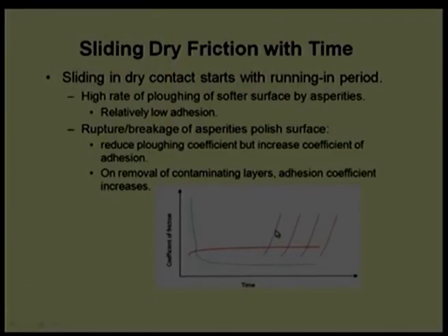It may be, say, two similar pairs. One pair can show life starting, coefficient of friction decreasing, reaching a steady state condition, and then coefficient of friction increasing again. Another similar component, a similar material pair, in another condition can show reaching this condition, moving straight, and finally ending with this line. It depends on the environmental condition which line will be selected, or there is a possibility of extended life, or many times we get infinite life. That is also a possibility. It will show a steady value of coefficient of friction throughout its life.